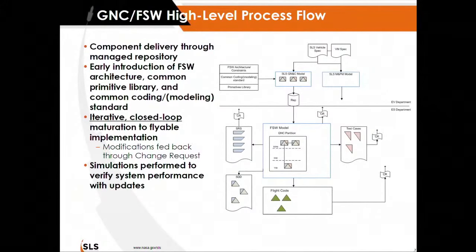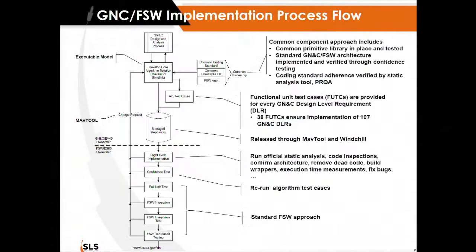And then from that, the delivery of software, we sit inside of our GNC portion of here, and then from that testing area, you can get CRs back to us from that testing. Integrated flight testing gives us CRs back, and also testing our unit test cases. There's a lot of methods where, as assumptions we've made about how it runs on the hardware, we've had to iterate with that. There's a capability on these paths to go back to our design for them to be formally tracked for this. And as we do our various simulations, we can track our performance towards our high-level requirements as we go through all this.